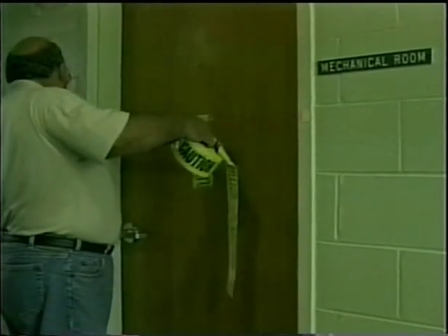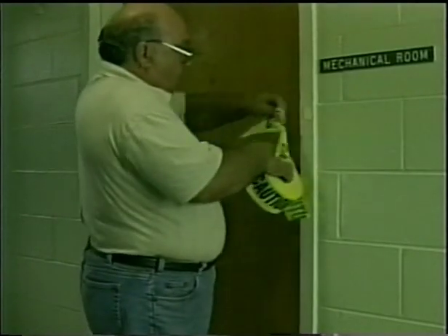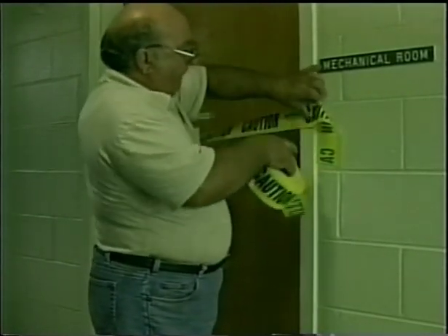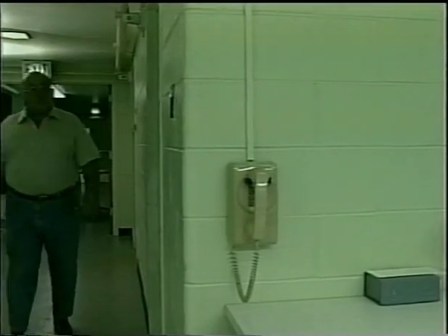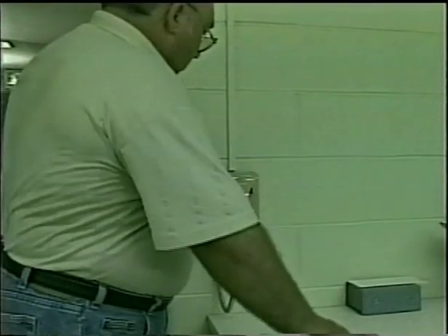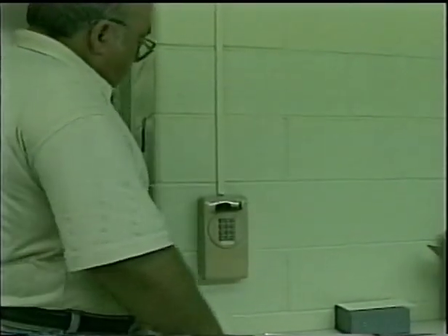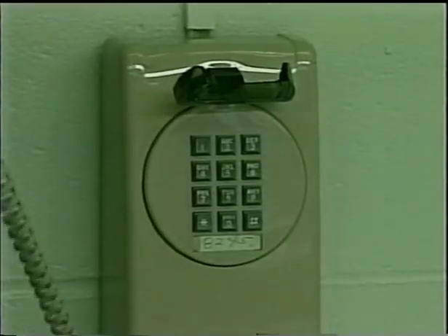If you have reason to suspect that something is asbestos, do not disturb it. Never drill, hammer, cut, saw, break, damage, move, or disturb any asbestos-containing materials or suspected materials.